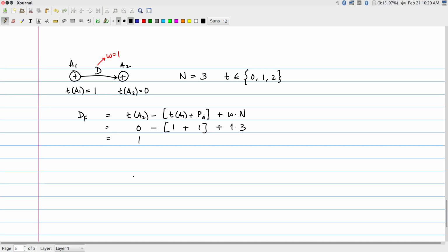Okay, what does my hardware architecture look like? I have an adder. Now I know that T of A1 is equal to 1, which means that I can straight away say from there A of n and B of n must be fed to the 1 inputs of the corresponding switches or multiplexers.